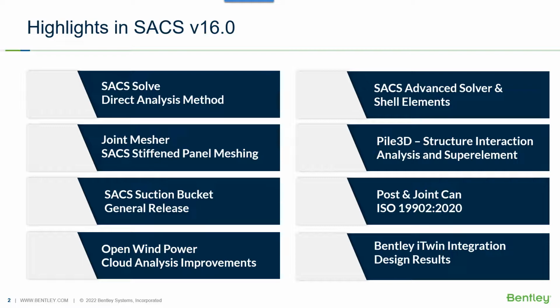First of all, the SACS server now accepts the elastic modulus reduction factor so that users can perform the direct analysis method suggested by AISC. The next update on the server side is removing rigid body motion for statically indeterminate structures. We also add a new type of shell element to the advanced solver. This is to prevent the rocking effect of highly curved shell elements.